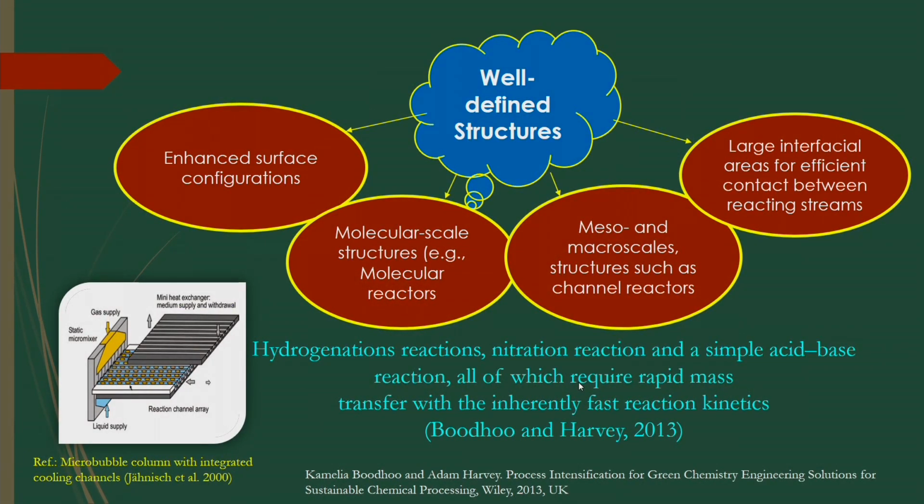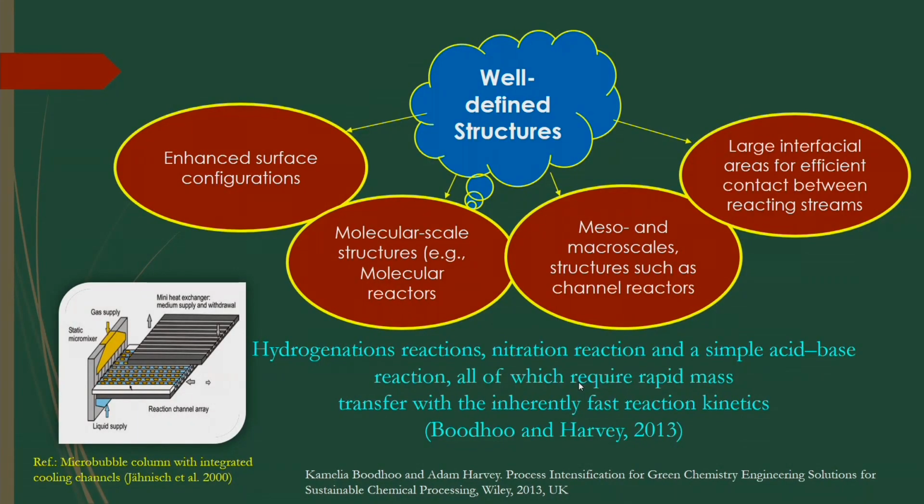Another important feature is called well defined structures. You have to develop the reactor in such a way that you make some internal provision inside the reactor to obtain more interfacial area for efficient contact between the reacting system, like packed bed, trickle bed, even some other microstructured packing materials through which the fluid will be flowing, getting more contact between the fluids and getting more mass transfer.